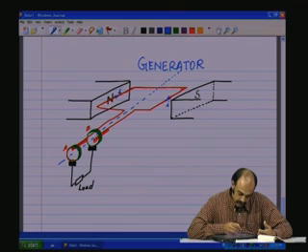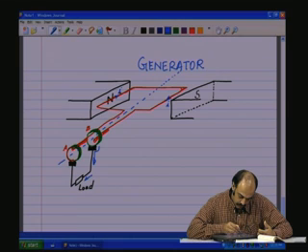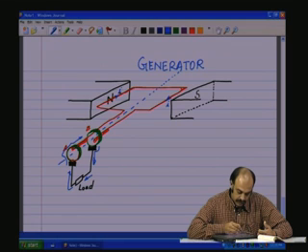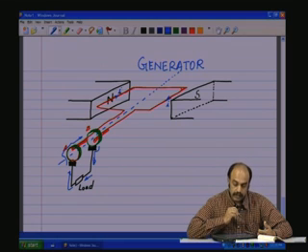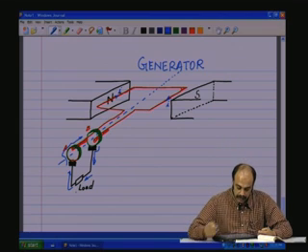This current flows through here, comes into contact through this brush, flows through this external load, and then flows in this direction, and then again flows into the other coil A through this ring and the soldered coil end, which completes the circuit, and thereby you get an output here.